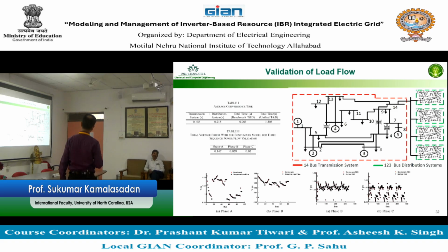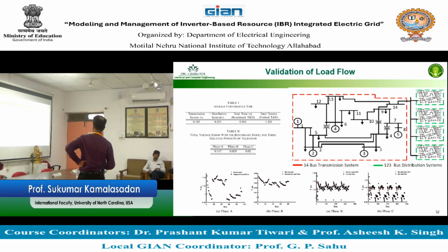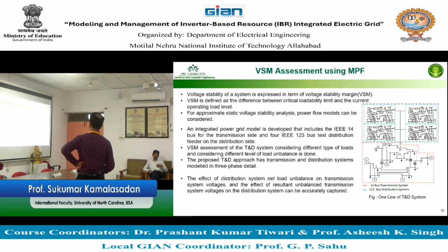You can actually add. So this is a case where we added 4 distribution networks on a node and then tested it out. This is a real IEEE distribution network, called the IEEE 123 bus system. You can compare that and then connect it with the transmission network, look at the phase error, the average. You also look at computational time because you don't want this to take 1 day or 2 days to solve. So that is something we tested, a few test results.